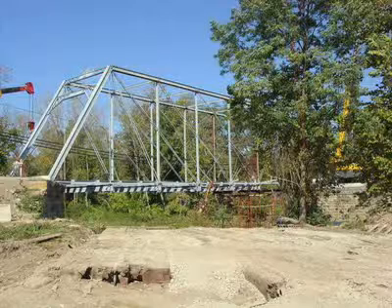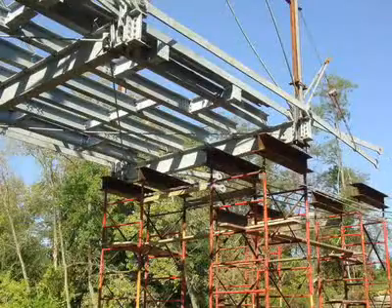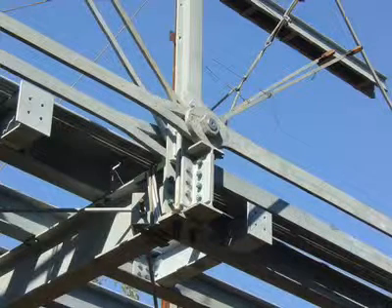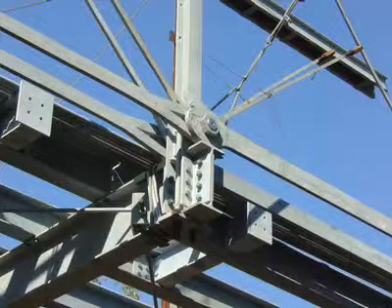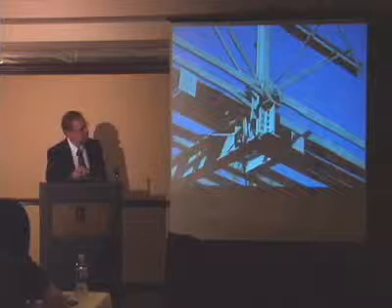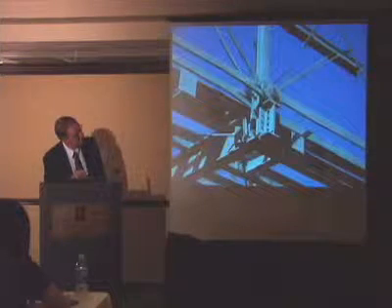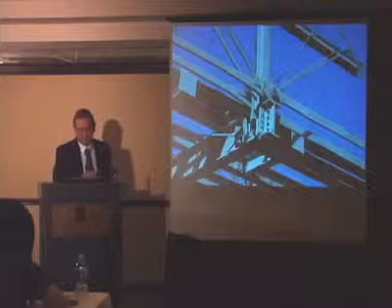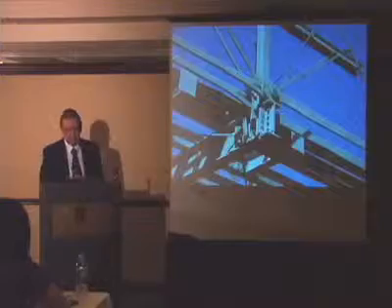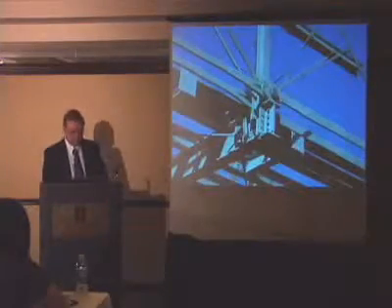The abutments, of course, were reworked and poured with the same kind of form liners as on the other bridge. There were new floor beams, new gussets, some new verticals. There was actually a lot of these plate bottom chords replaced, although these are the existing. You can see some of the little nicks and scratches in them from the years it was in service. But it had new stringers, new floor.